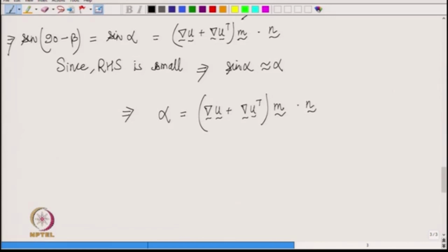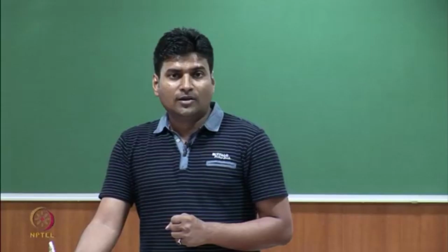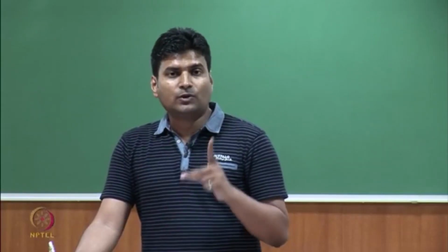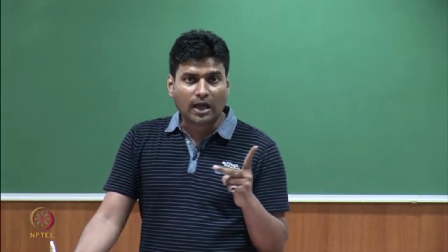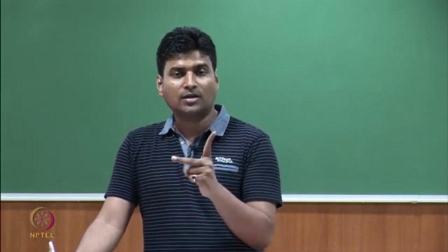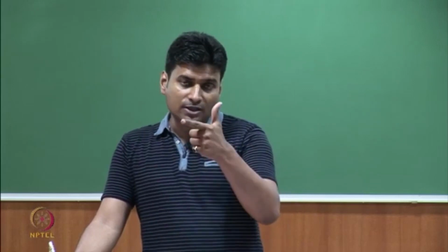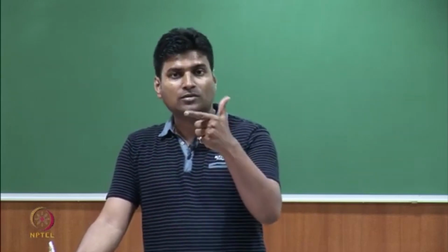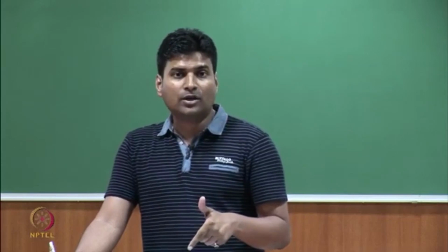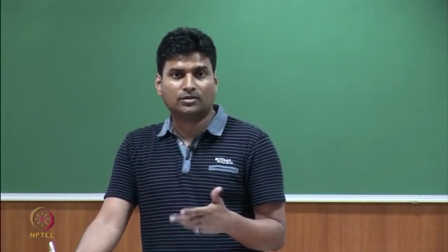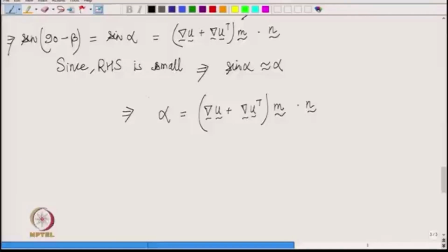So, we have now the formula in terms of the displacement u. So, to measure shear strain between two line elements, one along m and the other along n, you simply use this formula. As you change the two line elements at a point, the alpha that you get also changes, right. So, I will just mark it in red, that is the formula for shear strain.